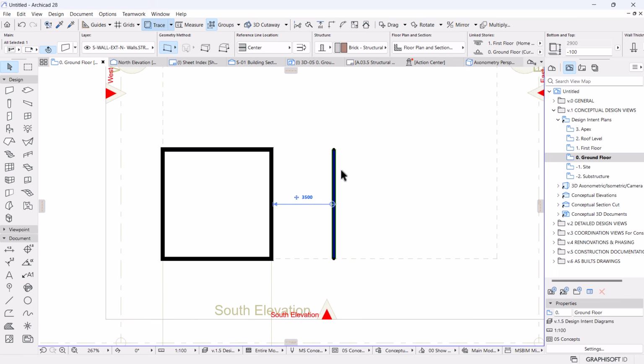I'm going to Control Shift D again to carry a copy horizontally to the right side of my cursor, and then this is where I want to position my staircase. For now, I'll set it around 3.5. It's subject to change once I'm placing my staircase.